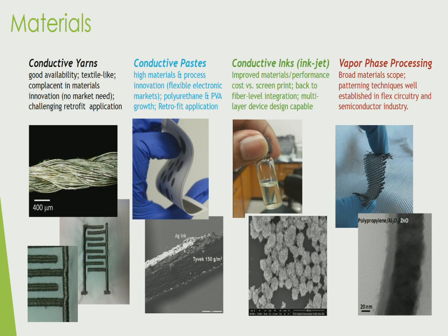Instead, the wearable electronics market has started to go towards conductive paste, and so these are screen print materials. Usually it's about a 75 to 85% loading of metal flakes within a polymer binder material, so it technically is a hybrid material. And they just pattern these materials out. It produces a layer that goes on top of the textile, and so it actually starts to get rid of those natural textile properties and starts to ruin the microclimate.